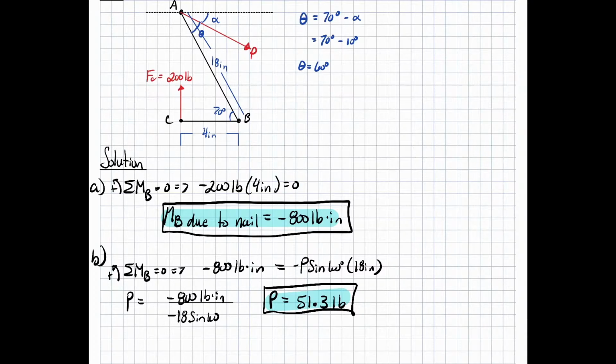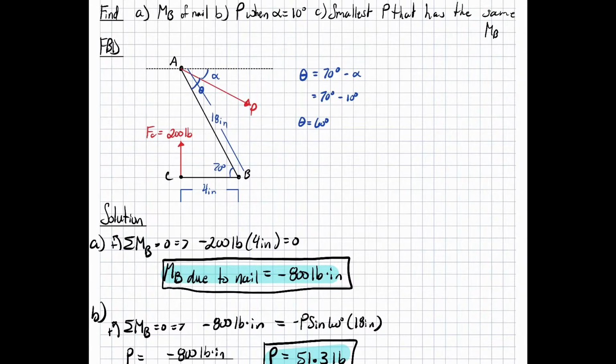But if you already know, based off the problem, that the moment is going to be clockwise, and you know that's probably going to be a positive value, you can state that it's positive clockwise. But when you're doing the analysis, you have to be sure that you visually state that you're saying that clockwise is positive rather than counterclockwise being positive. So it's all about how you state it. You can say counterclockwise positive or clockwise positive. Doesn't matter. Just make sure you stay consistent.